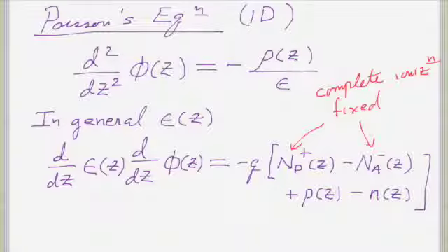Because heavily doped semiconductors go through what people call a Mott transition, and all the dopants stay ionized down to liquid helium temperatures. Or if you use the standard equations for whether they're ionized or not, they would no longer be ionized by the time you got below liquid nitrogen temperature.